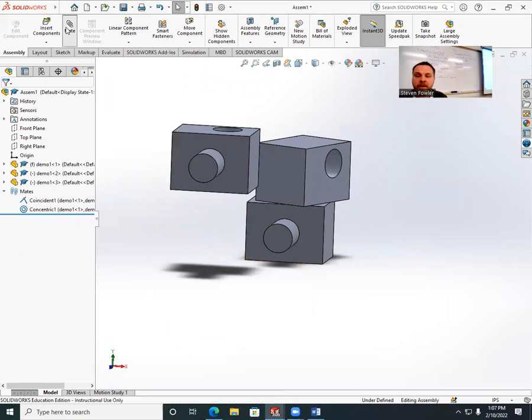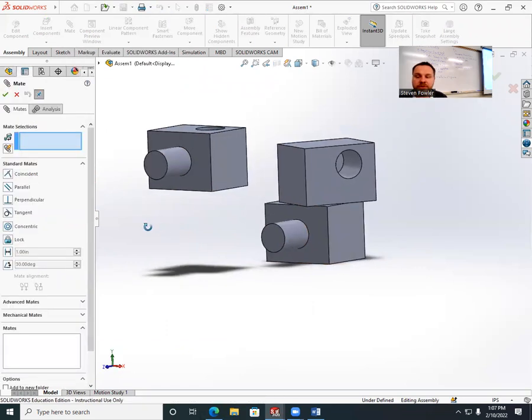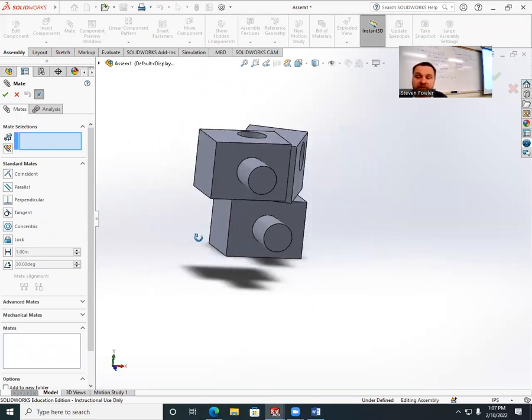So again, if I'm doing just coincident mates on normal surfaces, what I suggest to rookies is let's just mate faces to faces. You can mate lines to lines. You can mate points to lines. You can mate points to surfaces, a variety of things. You don't have to go face to face, but I'm just going from experience, and you're more than welcome to experiment with that. I'm not telling you you can't. I'm just going to teach you guys mating faces to faces, and then you'll kind of figure out more as you need to. Okay. And the tutorials will show you some more as well.